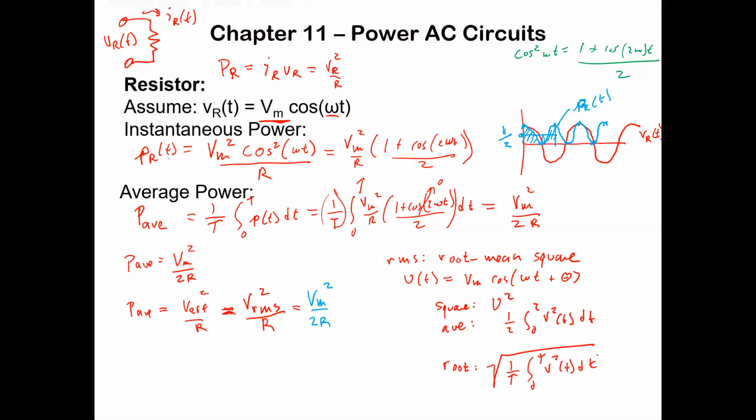And what's interesting about root mean square is if you take the root mean square of the AC voltage waveform, then you can find power by just taking VRMS squared over R in a similar way that you would for a DC voltage. And so when we talk about VRMS, that's the effective voltage that gives you essentially the same power that you're getting from the AC signal. So basically, the way I like to think of it is, as an example, okay, suppose, let's put an example here.